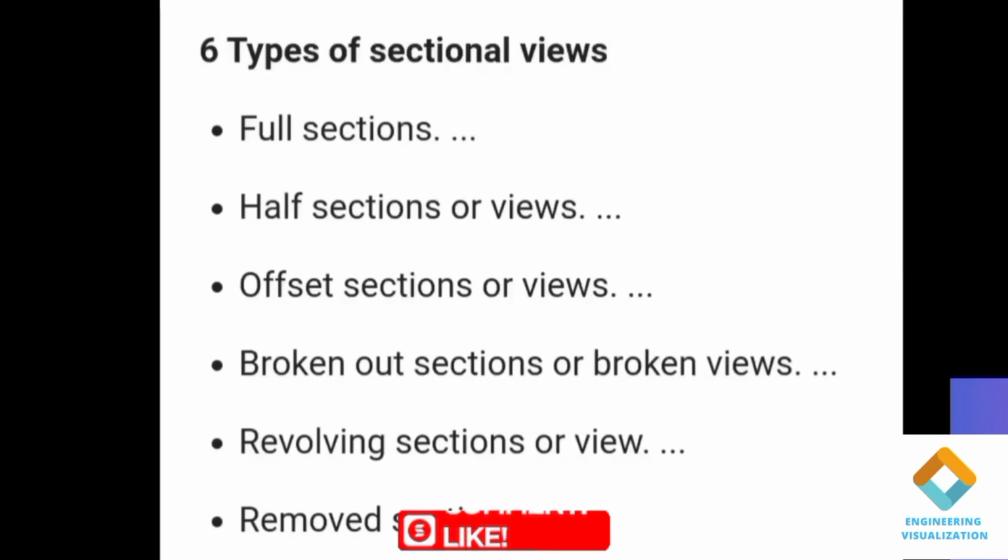There are totally 6 types of sectional views. First one is full section, second is half section, third is offset section, fourth is broken-out section, fifth is revolved section, and finally the sixth one is removed section. Each one of them we are going to discuss one by one with respect to the diagram, and how the section is cut and why each of these sections is cut in a different manner.